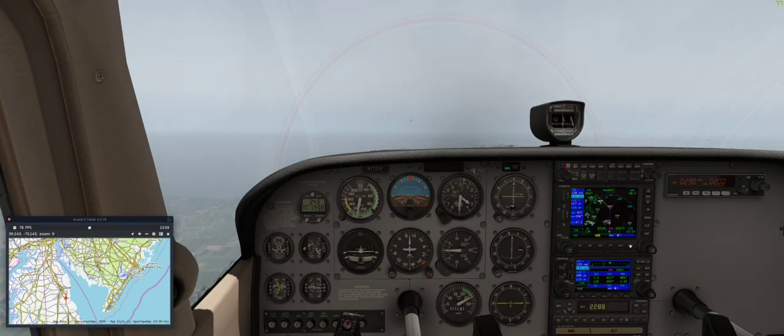Procedures, let's talk about that while we're waiting. The procedures button gets you into the menu where you can select approaches, arrivals, departures, and activate approaches if you have already one in. We don't have any. If I say select arrival, it knows that our arrival airport is KBLM because it got that from our flight plan. Let's see what arrivals are available.